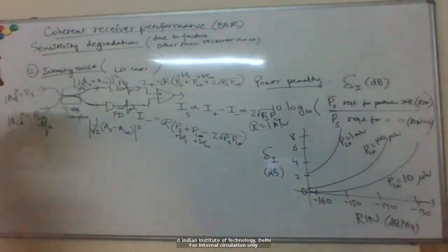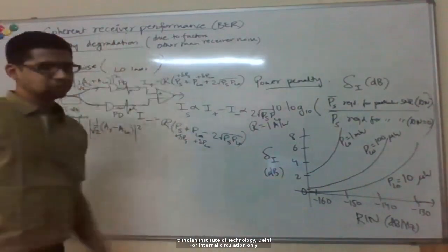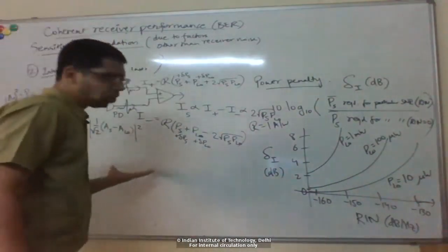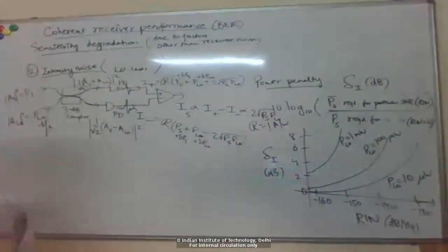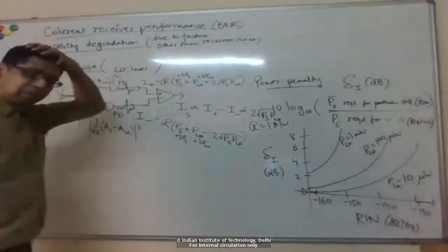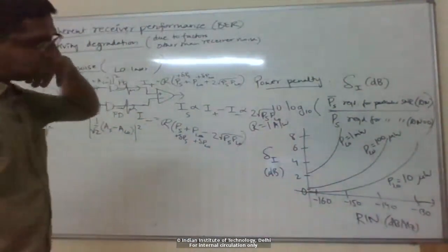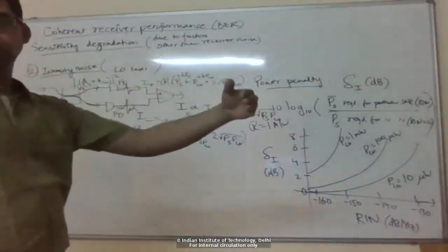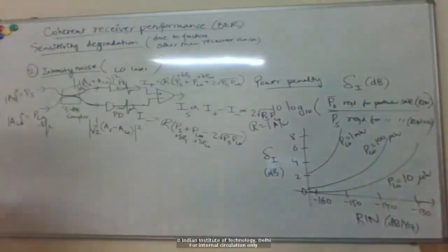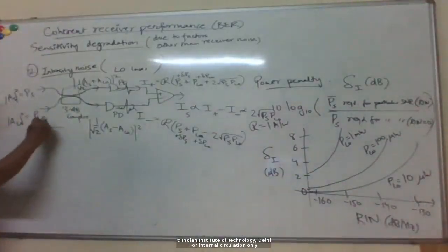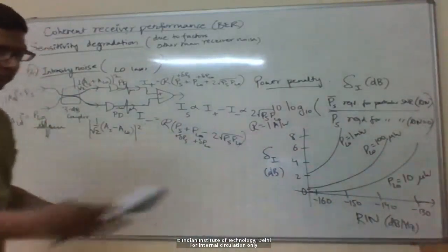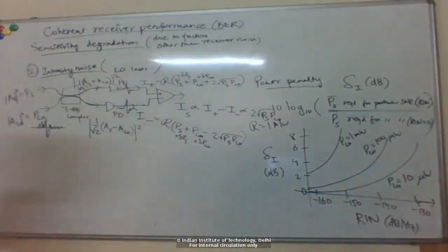Okay, so that seems great, and this is true, but not entirely. Okay, you reject all the noise up to when you reach what is known as shot noise or the quantum noise. Again, this noise in the optical power can come from various reasons, right? Technical noise sources like temperature fluctuations, mechanical fluctuations in the cavity, drifts in the current into my laser, etc. Right?